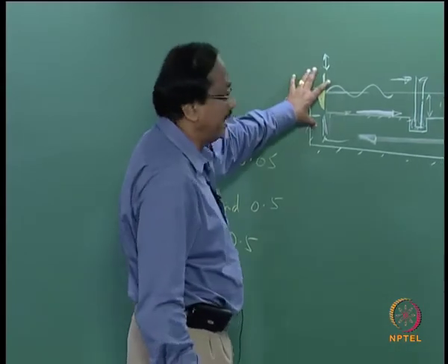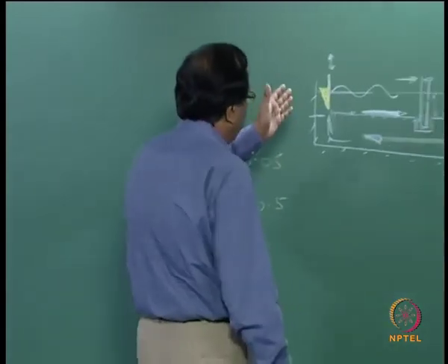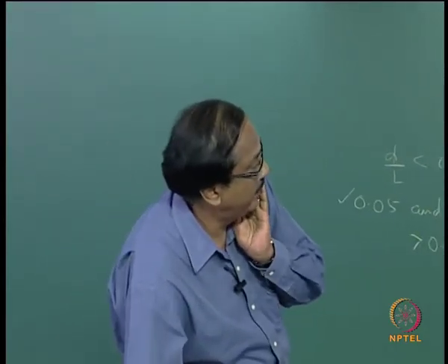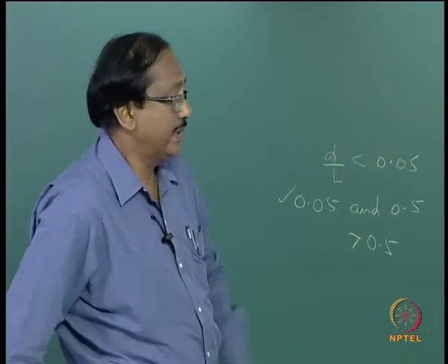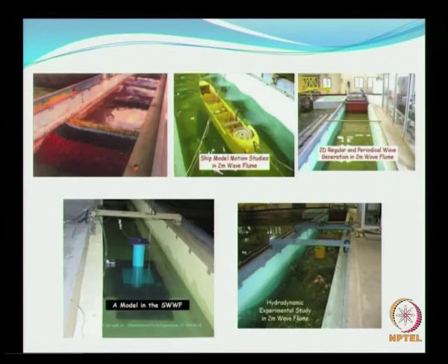Since we have gained enough experience with handling regular waves, we wanted to remove this and have a random wave maker. So this was a wave maker installed in the mid 90s that can generate both regular and random waves. So here you see some flume studies. Here the structure is placed wherein the forces are being measured on a pile, a large diameter pile, and here again a similar kind of study is being carried out.